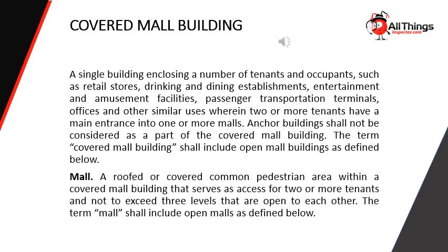Covered mall buildings, a single building enclosing a number of tenants and occupants, such as retail stores, drinking and dining establishments, entertainment and amusement facilities, passenger transportation terminals, offices, and other similar uses, wherein 2 or more tenants have a main entrance into 1 or more malls. Anchor buildings shall not be considered as part of the covered mall building. The term covered mall building shall include open mall buildings as defined below.